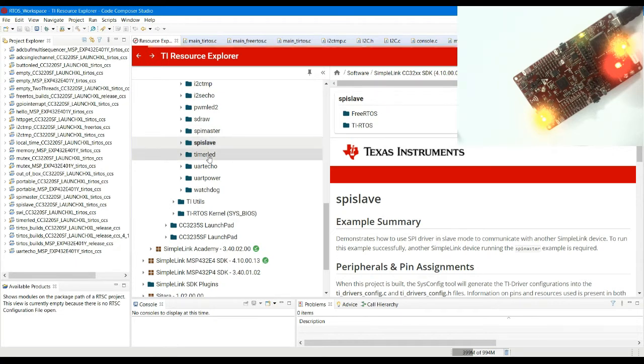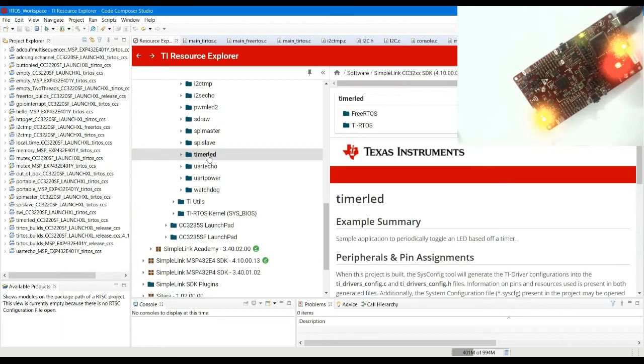There are also timer related examples, wherein periodically the timer will be expiring and generating an event, and there will be an LED handle that will be created, and through that LED handle we can control the toggling of an LED. The timer element which will be created, we can create it in one of 2 ways in RTOS. As we know, through the module we can create a static timer, or we can also create a dynamic timer object.